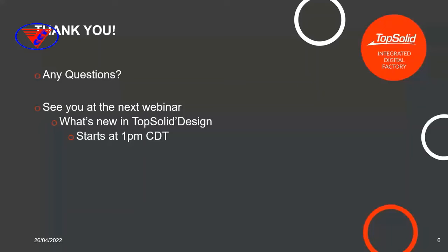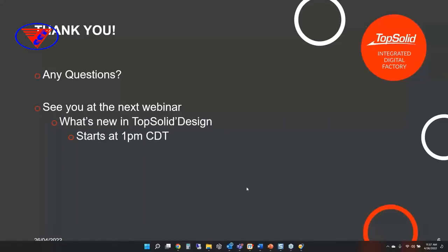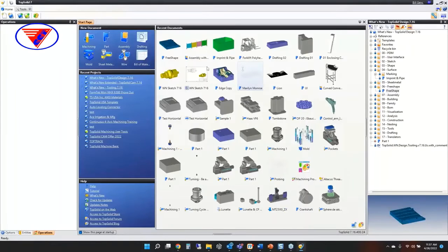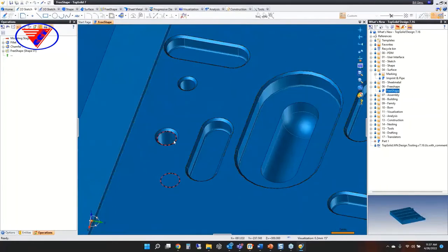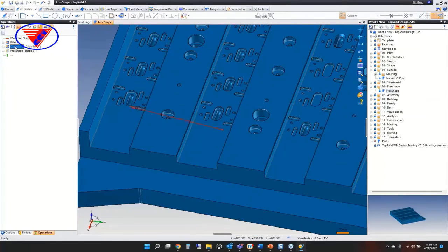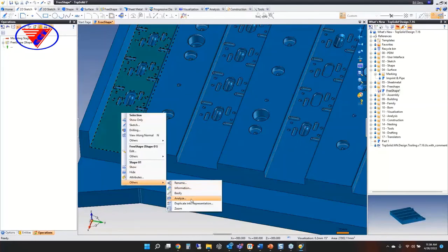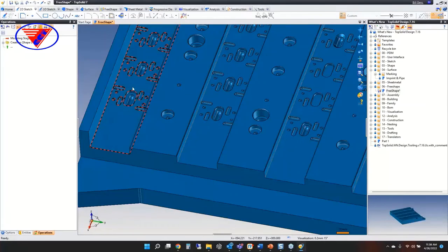So, did FreeShape remove the existing holes? I believe I answered that before, but yes, it removes them. Here, let me just hop back there really quick and I'll show you. Let's go back to FreeShape. So here, again, dumb data, other than, like I said, there was a chamfer and a fillet put on these features. Okay, we can even remove those. So here, completely dumb. Let's bassify. So everything in here is like it's an imported model.